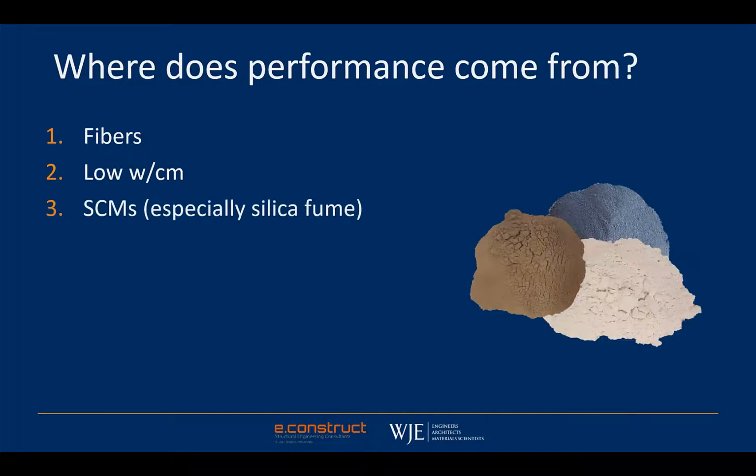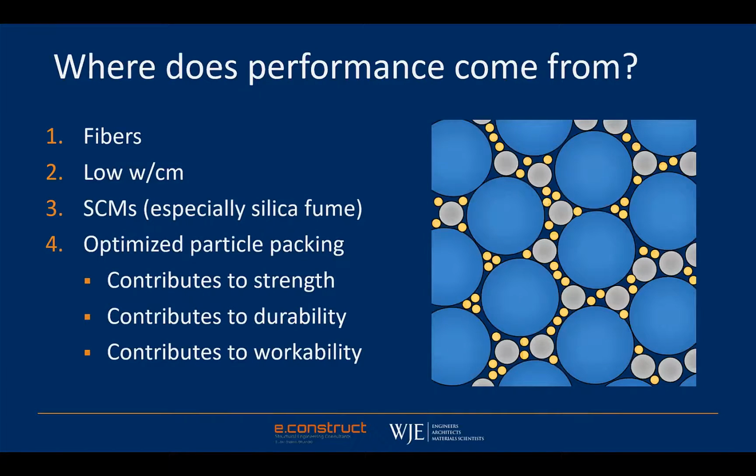Third, the supplemental materials included in the mix, especially the silica fume, bring useful properties to the mix, and perhaps most importantly, they allow for the fourth item, which is particle packing. So what we're trying to do with UHPCs is optimize the particle distributions to get as dense a material as possible, so smaller particles fitting inside larger particles, basically leaving the smallest amount of void space as possible in the matrix, and that contributes to the strength of the material and the durability of the material.